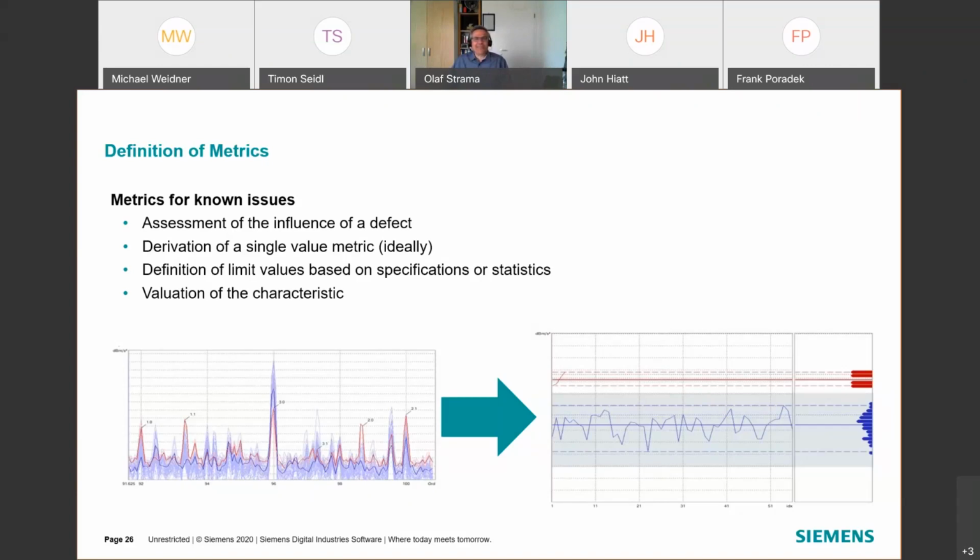If you talk about a contact sensor, then if I have a very rough surface, of course the wear of the sensor may be affected. But the sensor has a hardened steel tip, so it will work even under these conditions. But if there are really very rough structures, this could lead to signal disturbances at the accelerometer. But if you look at the laser, as long as the reflection is good enough, as long as I get enough light back in the laser, then the influence of these defects is quite small.